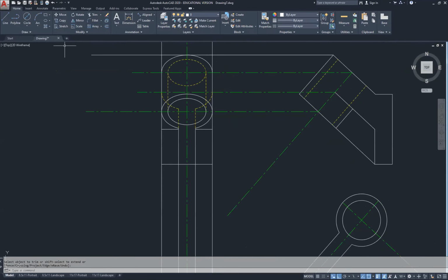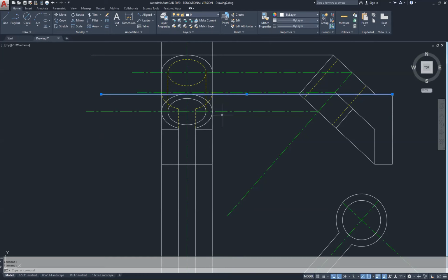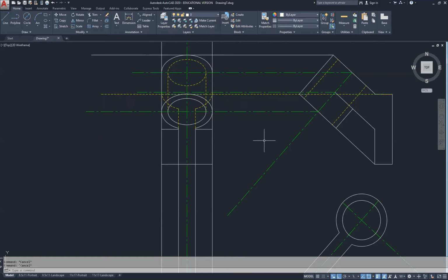And my last line I need to project is this back corner right here, coming across. This is going to be a hidden line, so it's under the piece. Hidden. And I'll select this line and this line here as cutting planes for my trim to cut away at that hidden line. And trim this out here.